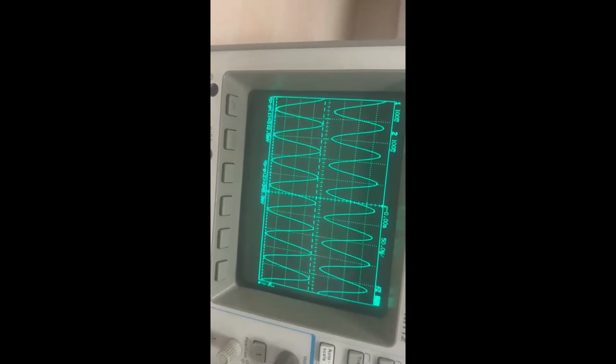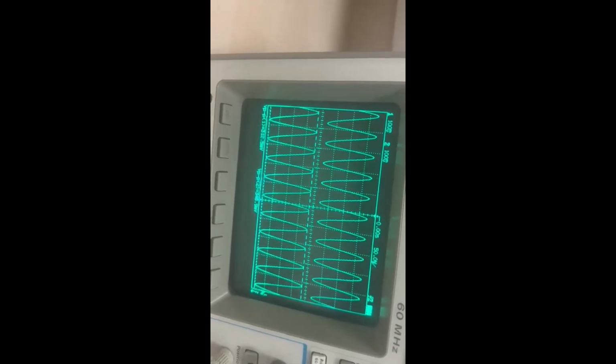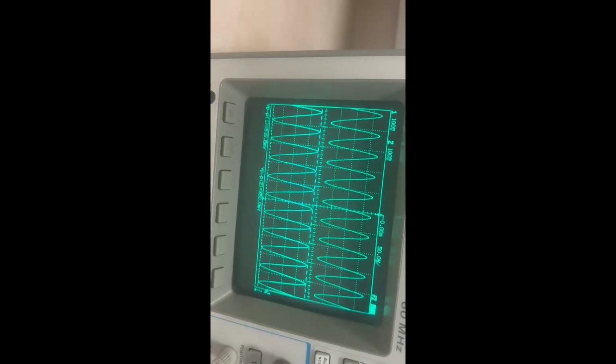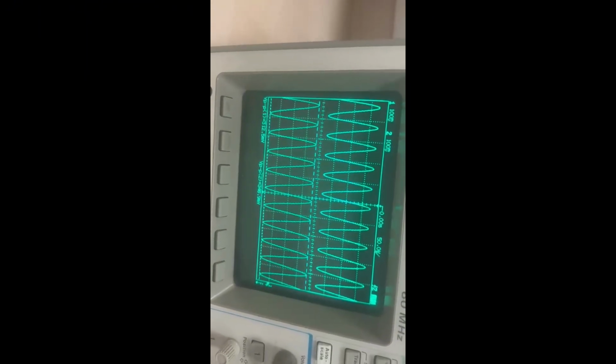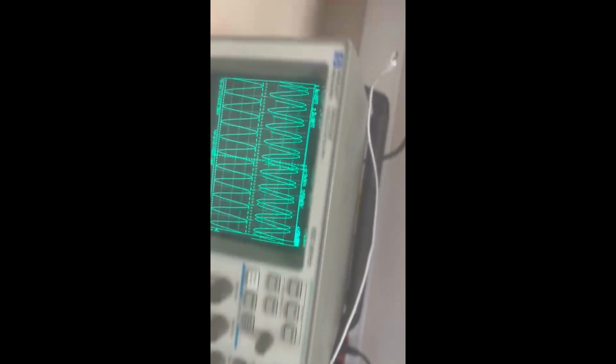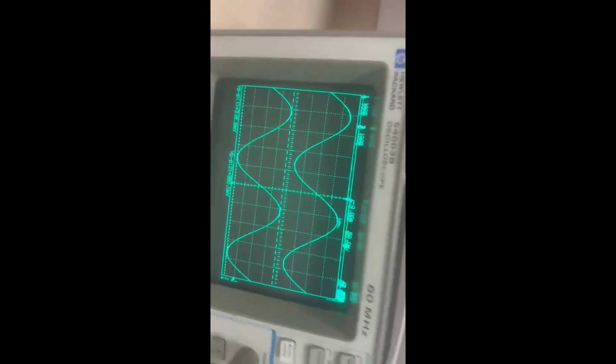Throughout the sweep, I monitored the amplitude of the output voltage. I specifically recorded the point where the output voltage reached its maximum and then suddenly began to drop. This critical point allowed me to identify the exact experimental resonance frequency for this setup. I repeated the same things for part B as well.